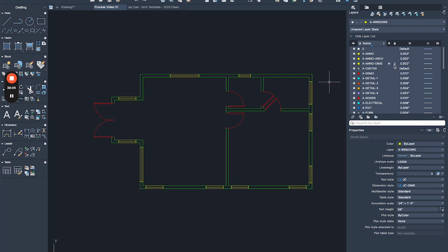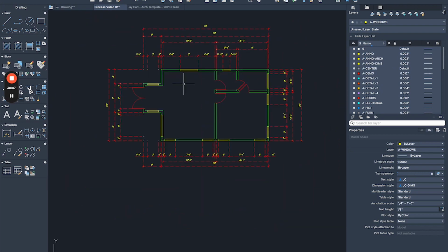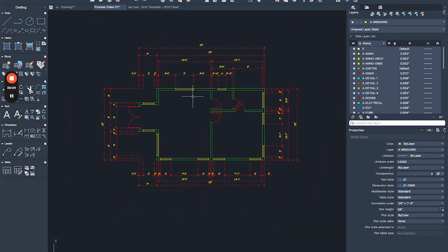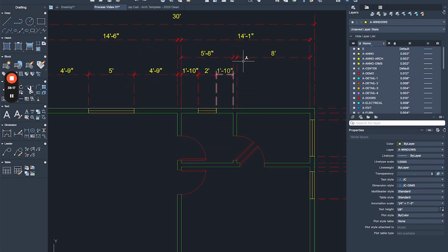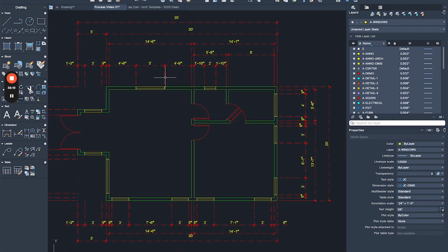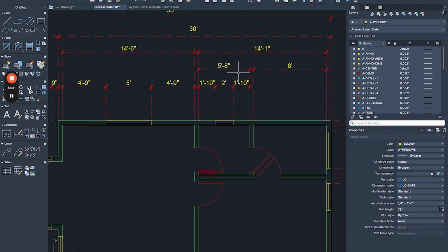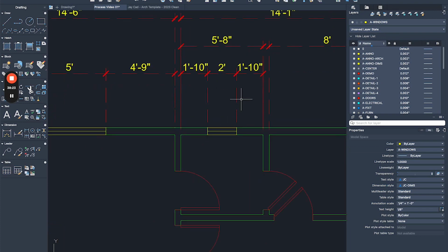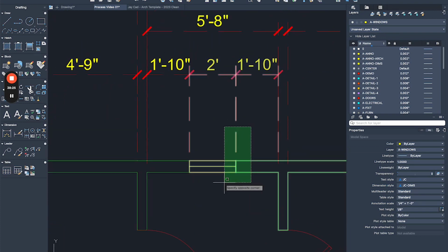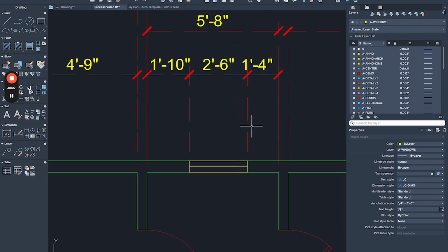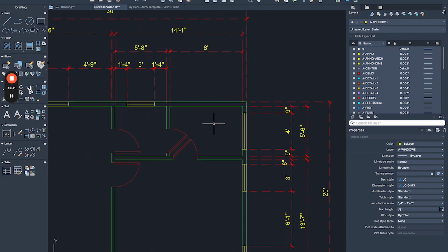Another save, and now let's look at the dimensions with them. All right, this is looking very busy already. Right, so you know how everything is now organized, everything is joined, and I have the dimensions. Let's say I'm going to send this to the client, and he or she is going to tell me, oh, can we make the laundry window bigger? So with stretch, and because I have the dimensions, I can easily make the adjustment, and everything gets moved in.